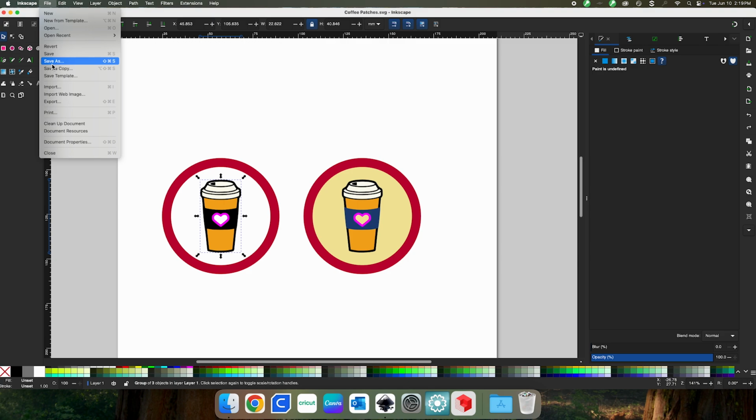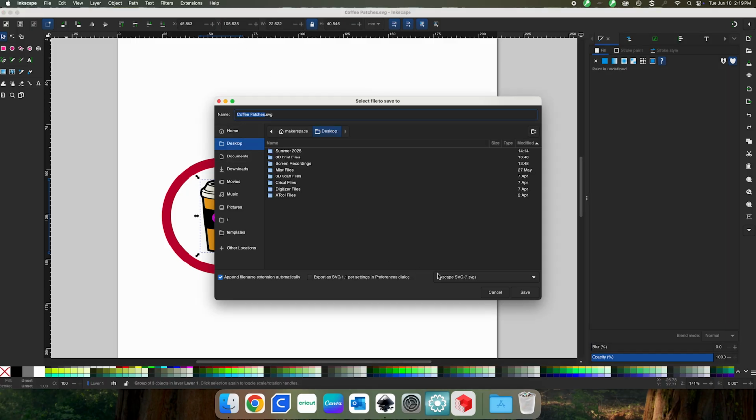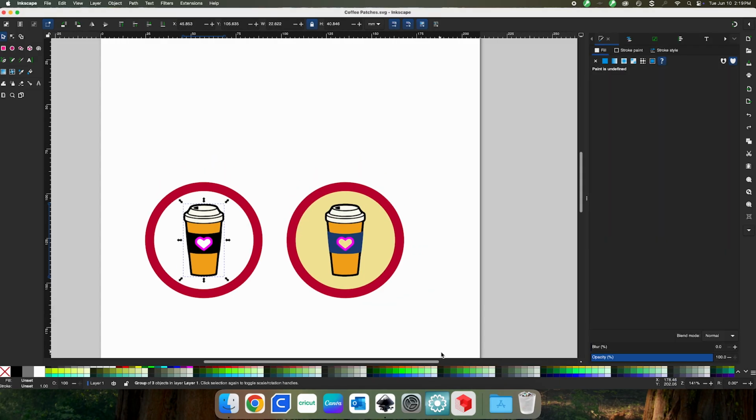You can select Save As from the Inkscape toolbar. You can give it a title and choose a saving destination. On our Makerspace desktops, you can save your files within the desktop folder associated with the current semester and the relevant equipment. You are welcome to create subfolders as you like. Make sure to save in an Inkscape SVG format. Artistic Digitizer can be very grouchy about accepting a plain SVG format.